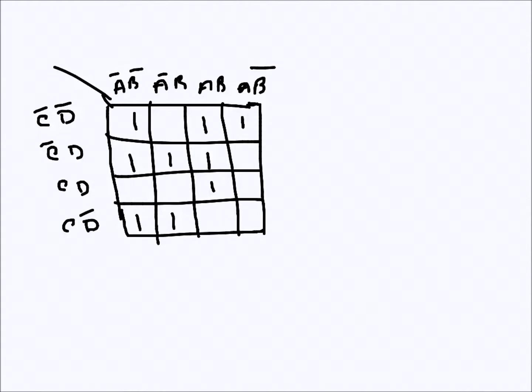all these squares in a K-map actually consist of adjacent variables. So from one square to another square, the variable that's changing is just one. So here it is a bar, b bar. So this square means a bar, b bar, c bar, d bar, while this second one means a bar, b, c bar, d bar.